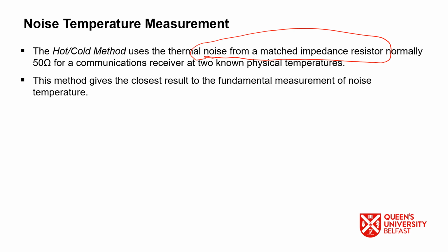So what actually happens is, imagine we have a receiver in which we have one amplifier or anything different, and then we are just connecting it to a scope. We will have one resistance connected to it. The noise that is created by this resistance is the input noise for this receiver, and the total output noise will be equal to the amplified noise Ni plus the receiver's own noise.